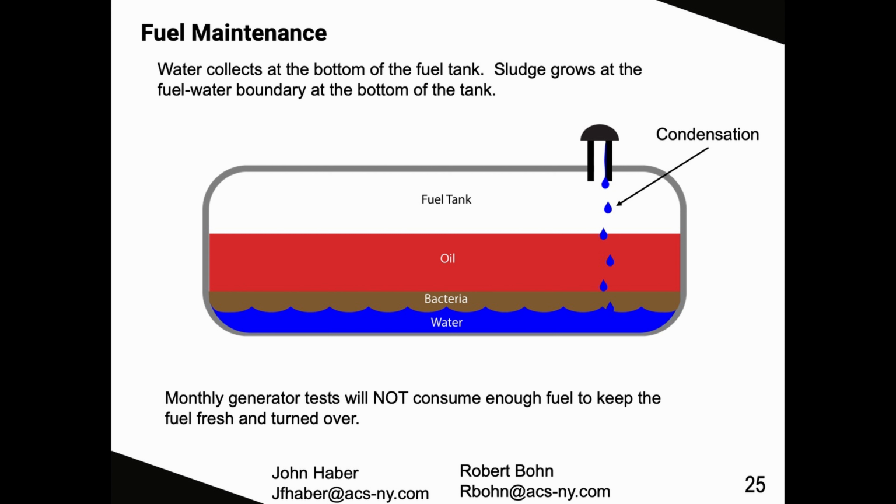Again, each generator has a 10 micron filter at the generator itself, and that's very small, so any of this bacteria or sludge that gets picked up in your fuel oil pump set and sent to your generator will get caught in the 10 micron filter and will shut your generator down. Filtration system prevents this and filters the fuel oil down to 5 micron.